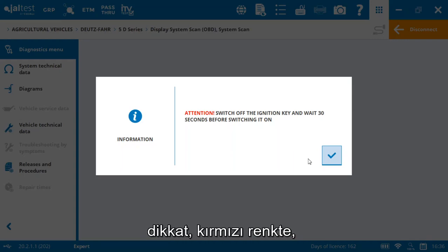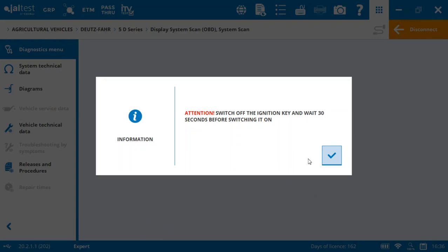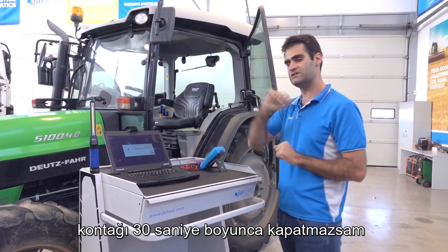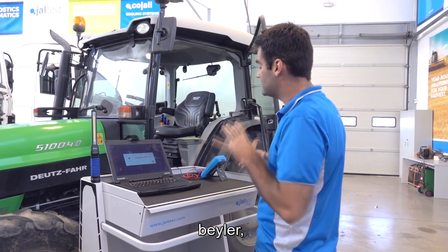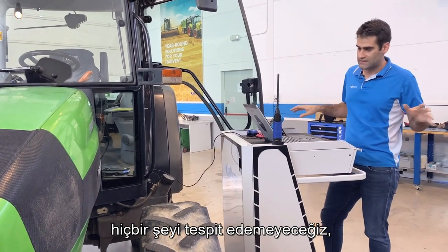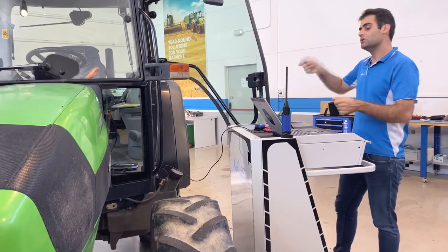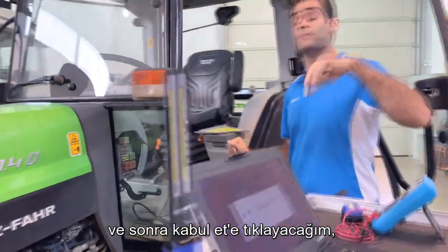See this message. Attention, it's in red color. Switch off the ignition key and wait for 30 seconds before switching it on. That's very, very, very important. Let me tell you, if I don't switch off the ignition for 30 seconds, you know what will happen? Guys, what will happen is we are going to detect only one system, or even we are not going to detect nothing. It's what it is. We need a little bit of patience with this type of vehicles from Deutz-Fahr. So I'm going to switch the ignition off for 30 seconds, and then I'm going to click on accept.